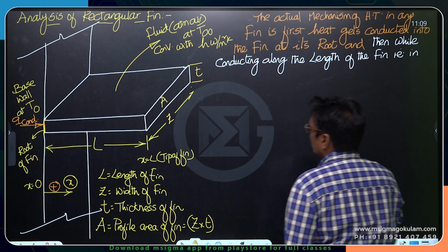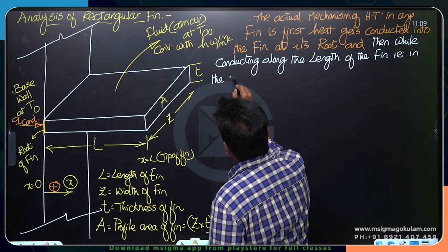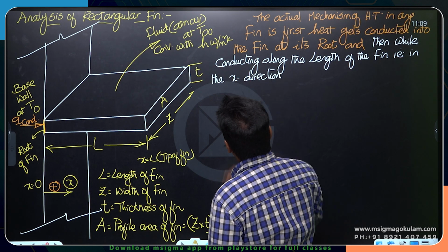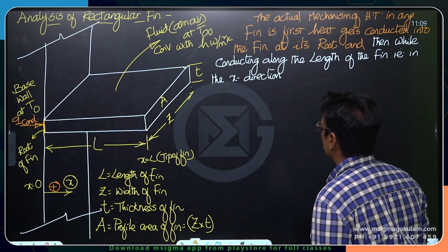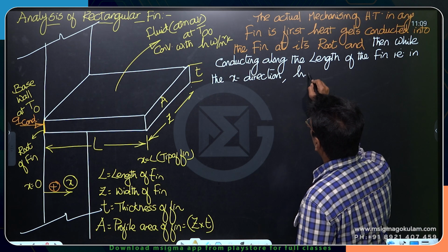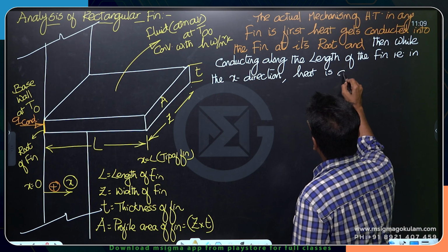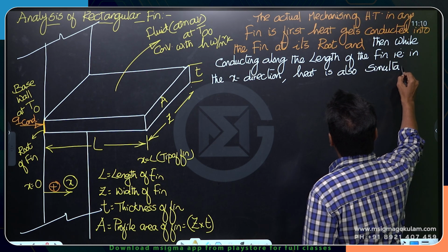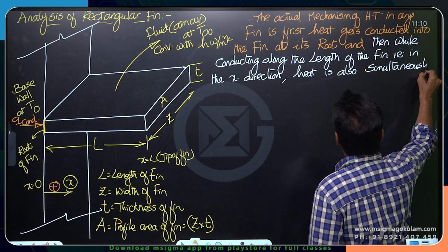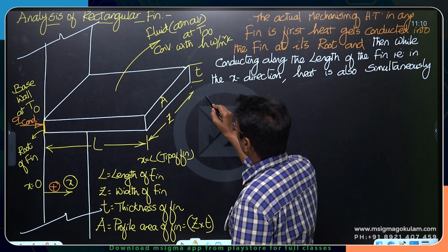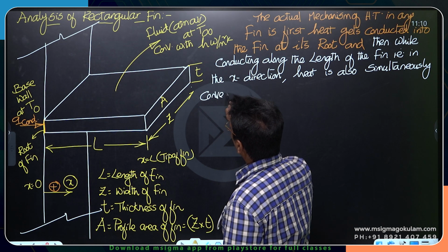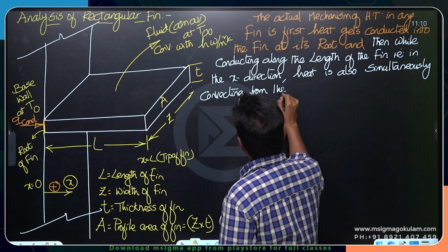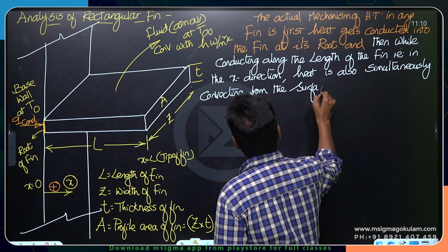And then while conducting along the length of the fin, that is in the x direction, heat is also simultaneously convecting from the surface of the fin.